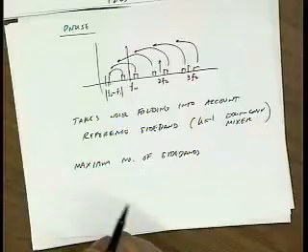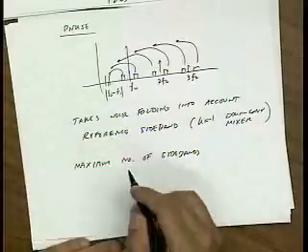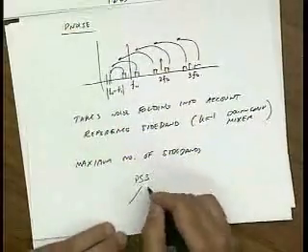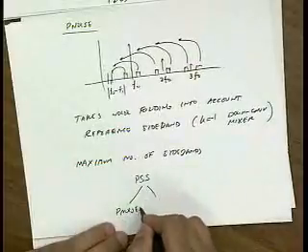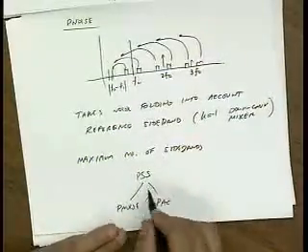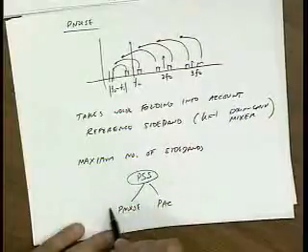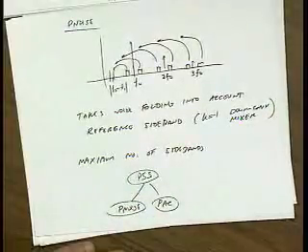Okay, questions about PAC, P-noise? So just like PAC, you first have to run your PSS simulation before you can run your P-noise simulation.